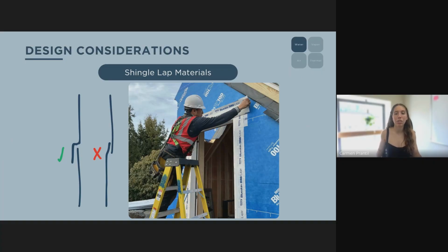And these continuous terminations are reliant on the workmanship of the sealant or the mastic installer. So if you have a reverse lap and the sealant is installed in a manner that is not continuous, it can provide a pathway in. Which again, if we're looking to kind of idiot-proof our designs, let's make it easy for ourselves, work with gravity, call out shingle lapping.